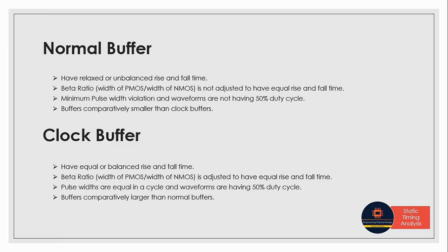So why do we need balanced rise and fall time? First we need to understand that. Because unbalanced rise and fall time will create skew, and that will again create further delay. So the circuit performance will get affected, and also more power consumption will happen.